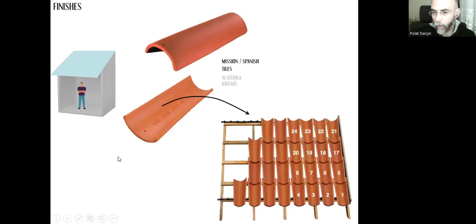First, we place them over the lats, looking upwards like this, open. Again, we start at the eave level, first line, and then once the first line is finished, we do the second line. And as you can see, the narrower end of the upper line will be placed inside the wider end of the lower line, and they're again overlapping, and they are slightly separated from each other. There's this slight gap in between these rows, let's say.